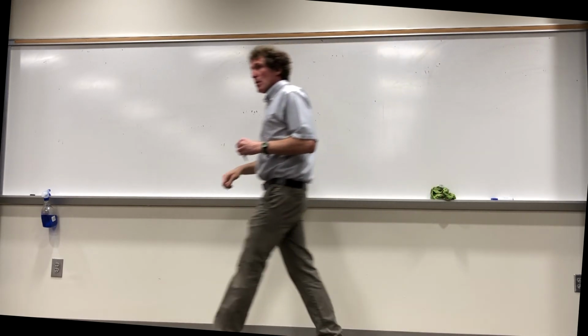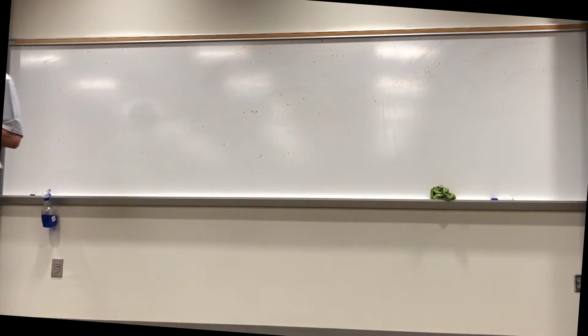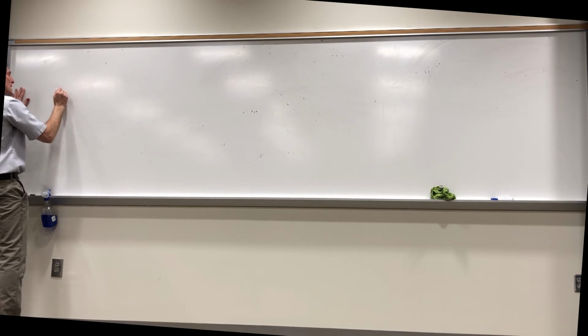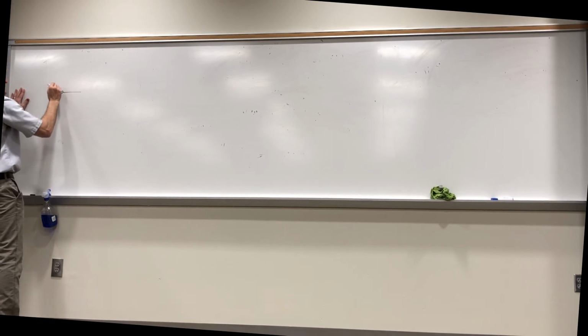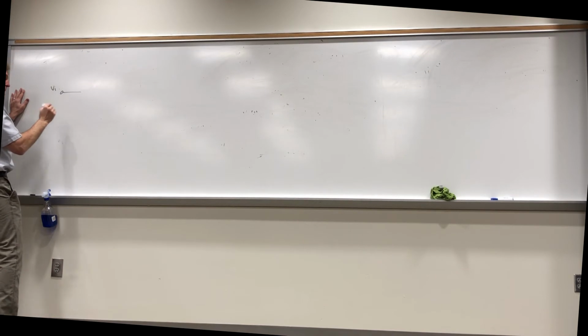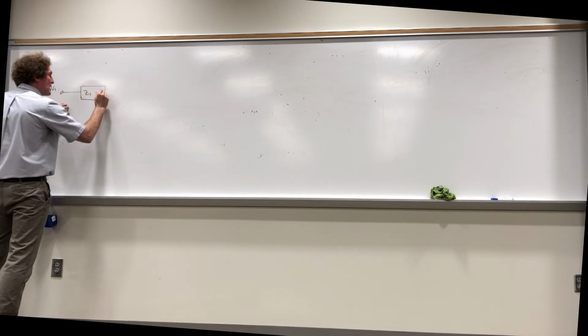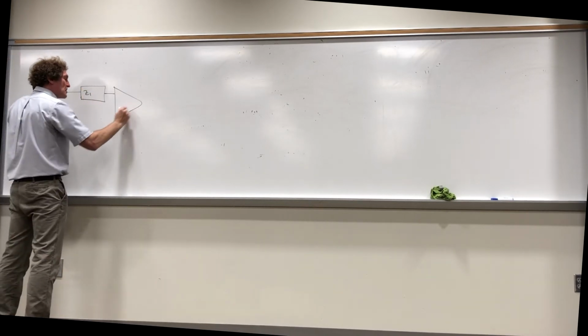So now I'm going to show you the most general form in the S domain to do analysis, or impedance domain. Remember, we're going to assume that we have an input here, V in, and we're going to have some input impedance. I'm going to draw a box here, call it Z1. And that goes into the inverting terminal.